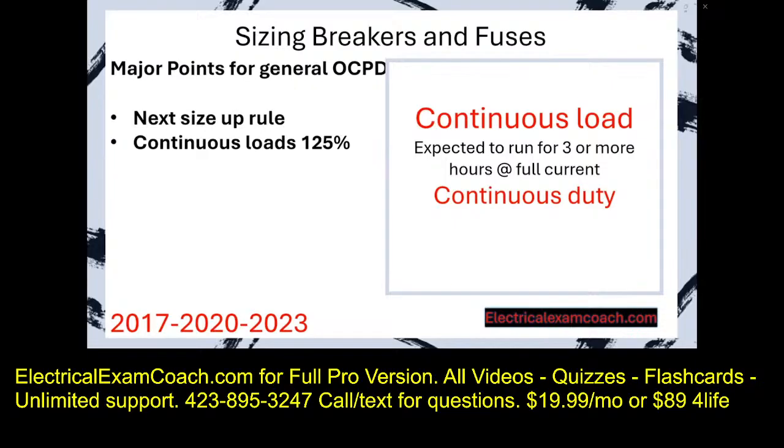And it'll ask you for wire size or breaker size. Or it might say 5 hours or 10 hours. It doesn't matter how many hours it is. If it's 3 or more, it's considered a continuous load. You may also hear the word indefinitely. Just to try to throw you off, they might use the term indefinitely. Well, it falls under the same classification of needing a 125% multiplier. Remember, it's just another demand factor.